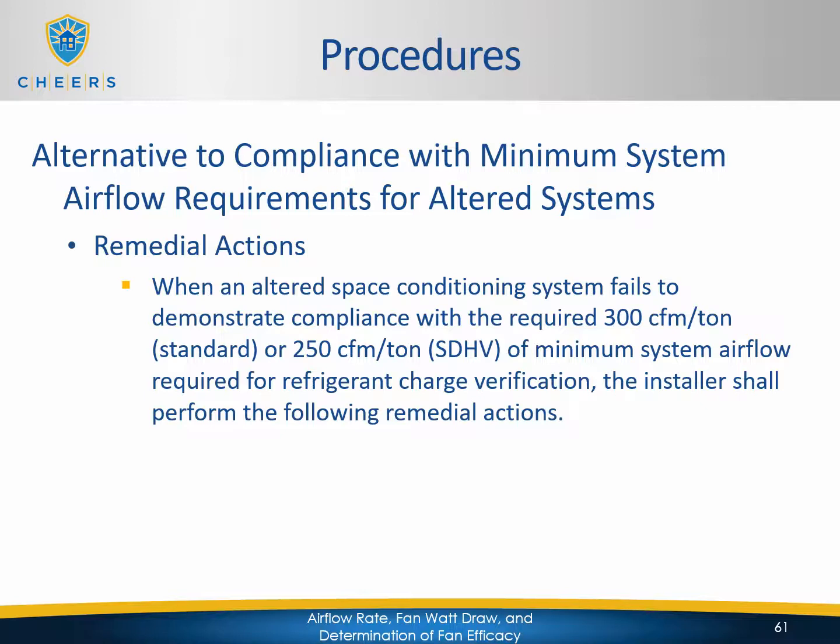This doesn't apply to all altered systems because we're not going to be doing airflow testing on all altered duct systems. We're only going to be doing airflow testing on an altered duct system for the purposes of verifying it for refrigerant charge. So part of the requirements for the refrigerant charge verification is a verification of the airflow for that system.